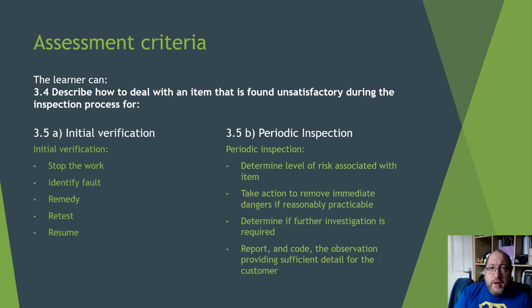So you stop the work, and then you identify the fault, you remedy the fault, then you retest to verify the fault is now clear, and then you resume. This is why we have a sequence of tests, so that we can actually stop at a point and not have to go back to the beginning and start again. We can just carry on from that same test that found the problem and push forward. If, however, your repair work introduced new cabling, new parallels, then maybe you want to go back and start some more subsequent tests. You know, a competent person would understand the differences with those. But you always stop, identify, remedy, retest, resume.